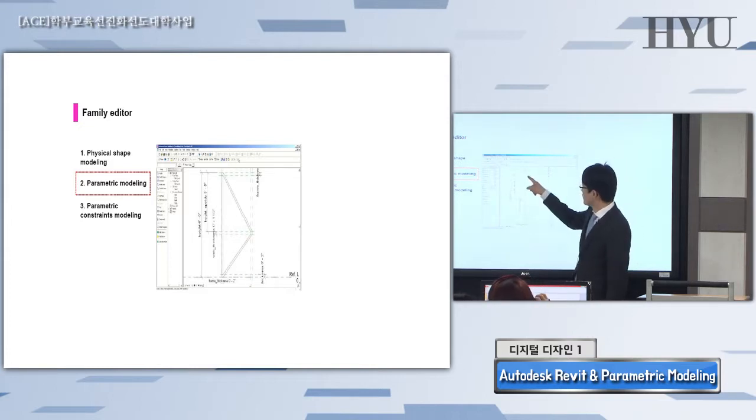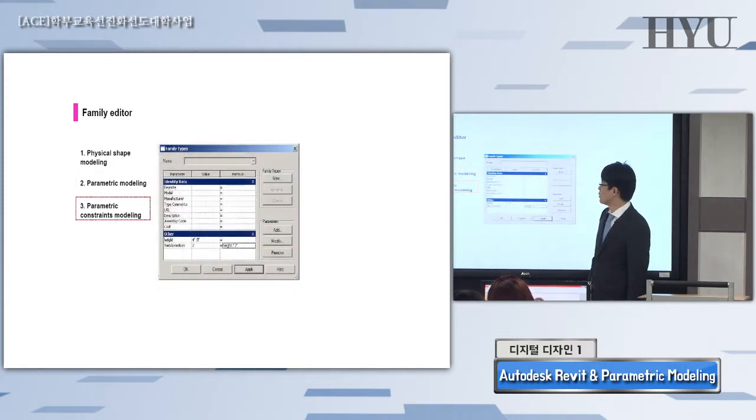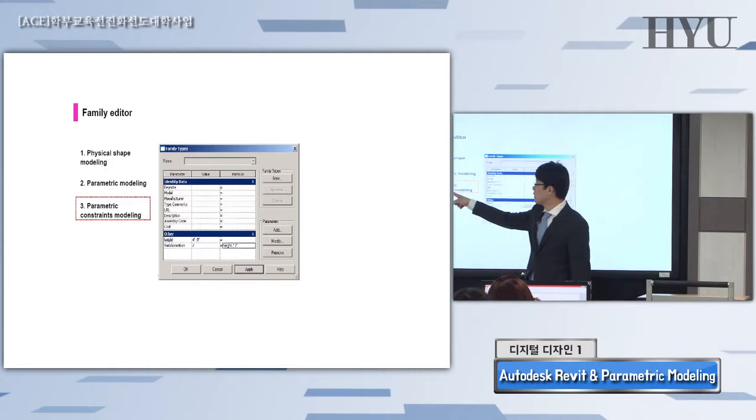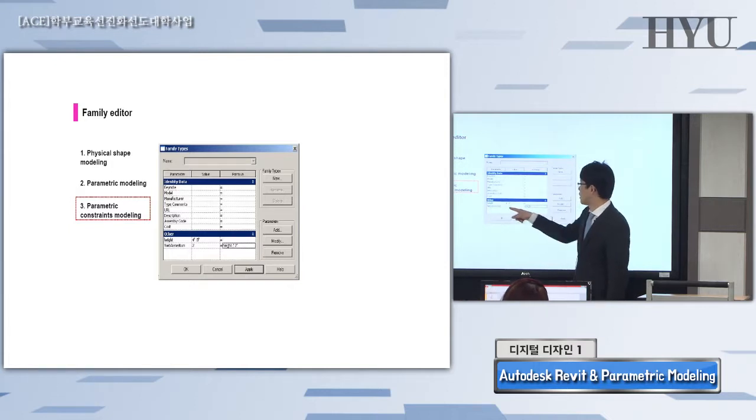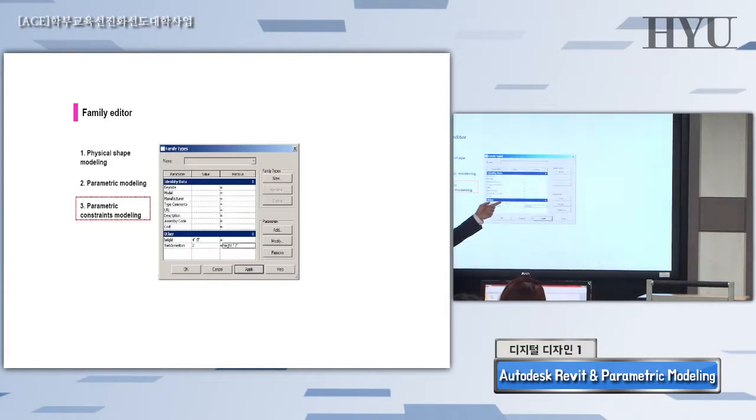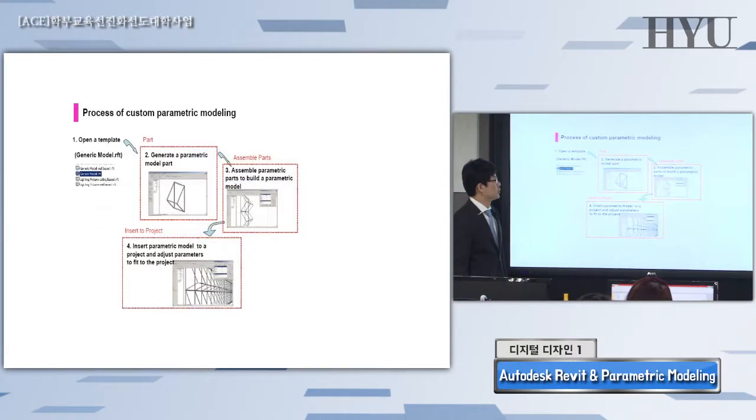A simple triangle shape, but parametrically defined: the ratio of this triangle shape, the thickness, the depths and so on. Define the geometry and put in the parametric constraints. Constraint means a simple equation, such as web thickness, web height going to be the same as the front seal's height and so on: equal, bigger than, or some numbers, okay? Very elementary school level equations for this model.